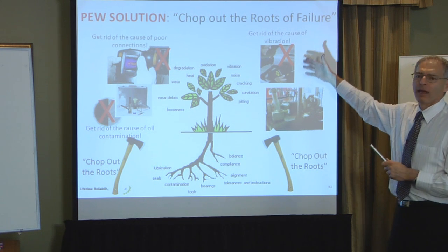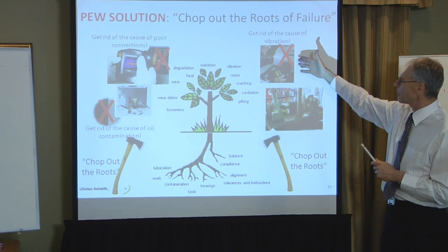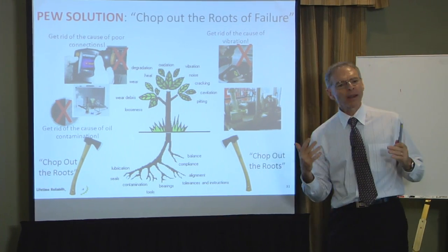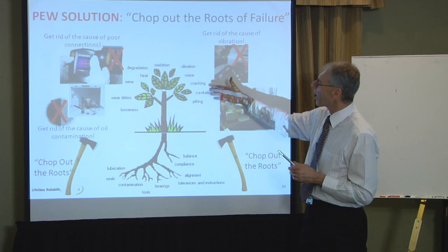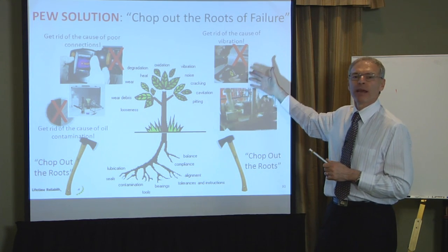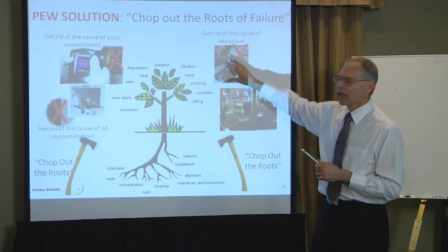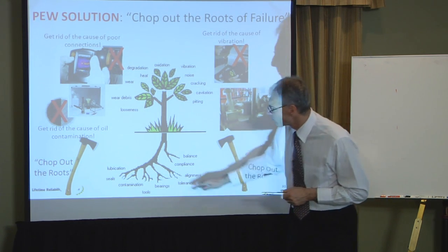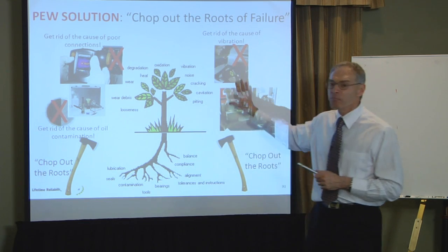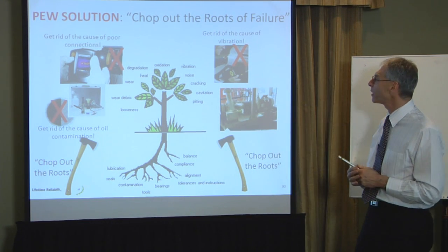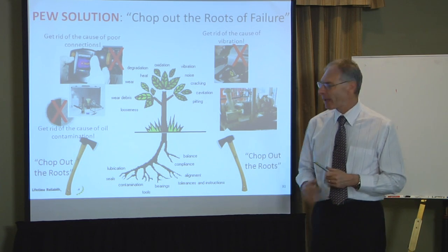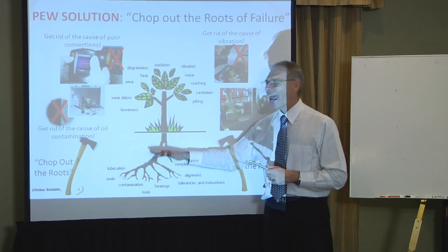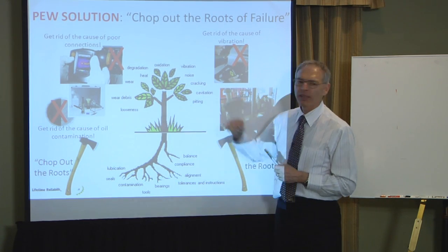Same with vibration analysis. Vibration analysis guy, he'll find a noisy bearing. He'll tell us, this motor's in trouble, you've got 2 months to go before it fails. That's wonderful. I've got a noisy bearing, high vibration, now I've got to maintain it, I've got to repair it, I've got to stop production, I've got to spend money. Had there been no unbalance, had there been correct alignment, had there been proper lubrication, no contamination, there would have been no hot bearing, would have been no noisy bearing in the first place. And PW is about working down here and staying down there, making sure things are right and are always right. So we don't have these troubles.